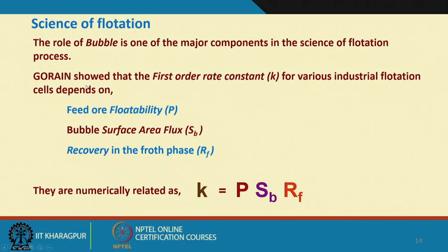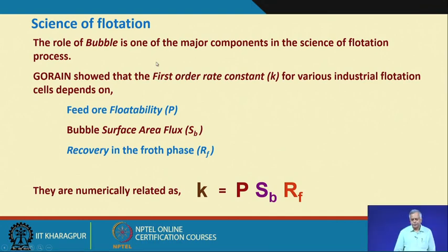A relatively newer research outcome. The Gorain, that is your name is Dr. Barun Gorain. He did this work in JKMRC, Australia during his PhD. The role of bubble is one of the major components in the science of flotation process. That is, you may have made your mineral surfaces hydrophobic, but it is the collection of these hydrophobic minerals or the separation between your hydrophobic and hydrophilic materials.